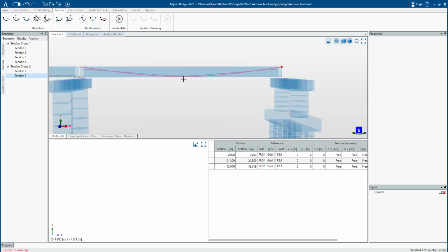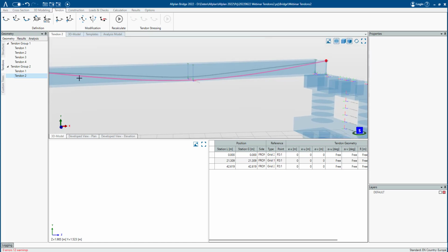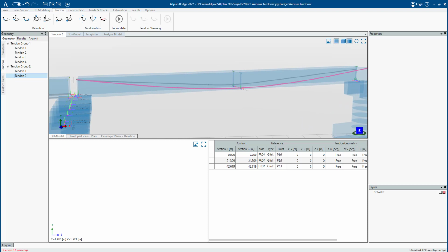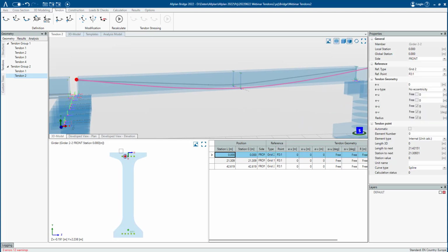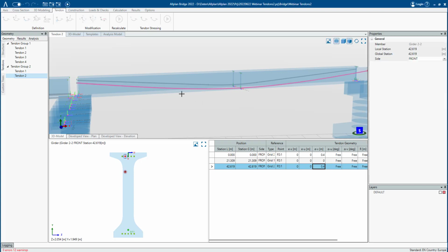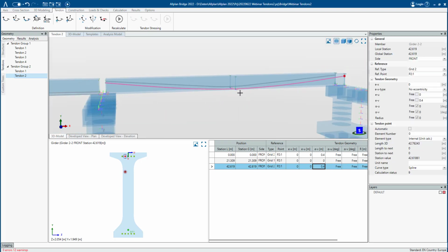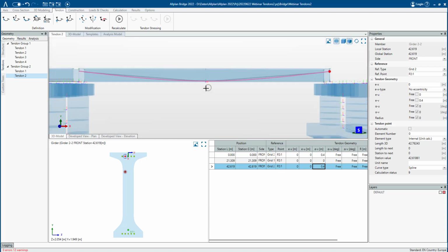Now you can see it has this curved form properly in place, and it goes from the upper edge, the upper end also here, and I don't want to have this, so I can adjust it very simply. In the V direction, I go further downwards. For example, it goes 40 centimeters at the end points downwards, recalculate it, and you see how quickly this is adjusted.